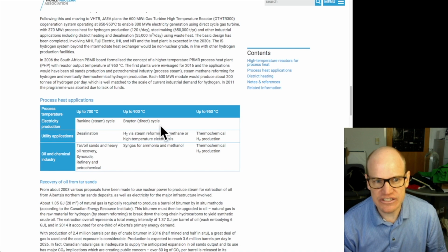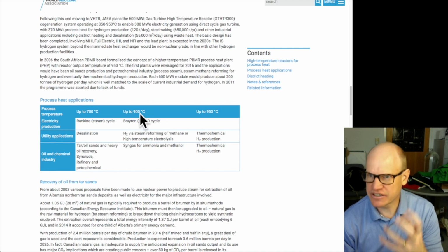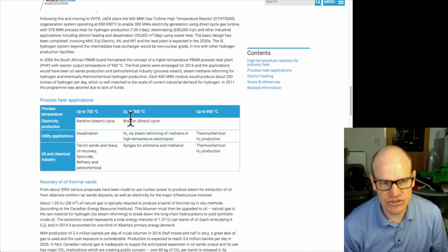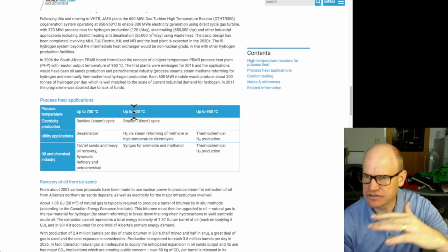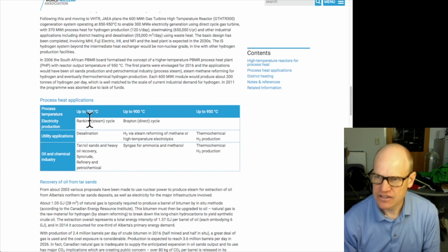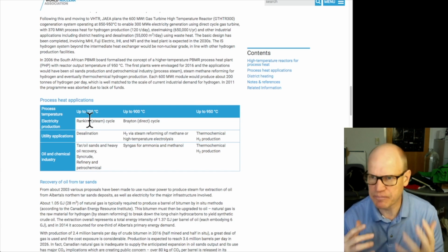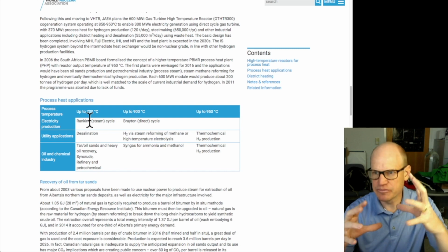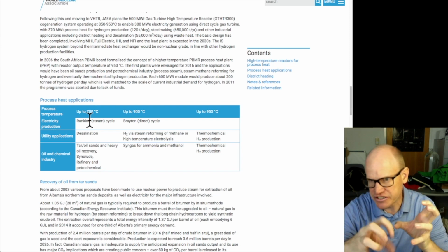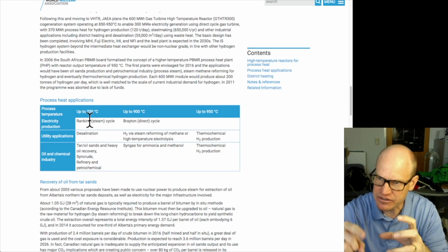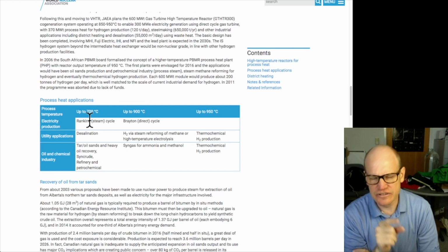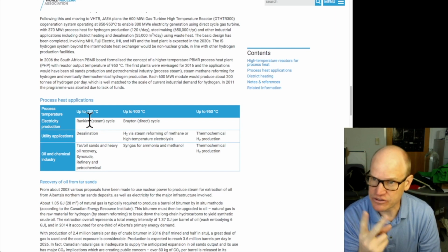One of the advantages of a natural gas power plant is that you can use the exhaust from the Brayton cycle. Even though the Brayton cycle itself operates at really high temperatures, the exhaust also comes out at high temperature. You might go from 900 Celsius and drop down to 500 Celsius, but 500 Celsius is still high enough to run the steam cycle. So you'll get what's called a combined cycle natural gas power plant. Combined cycle means you have a Brayton cycle, the natural gas plant running like a jet engine, and then you take the exhaust and feed it into a steam cycle, a second cycle where you get electricity from the exhaust of the first cycle. Some natural gas power plants are combined cycle and do both.